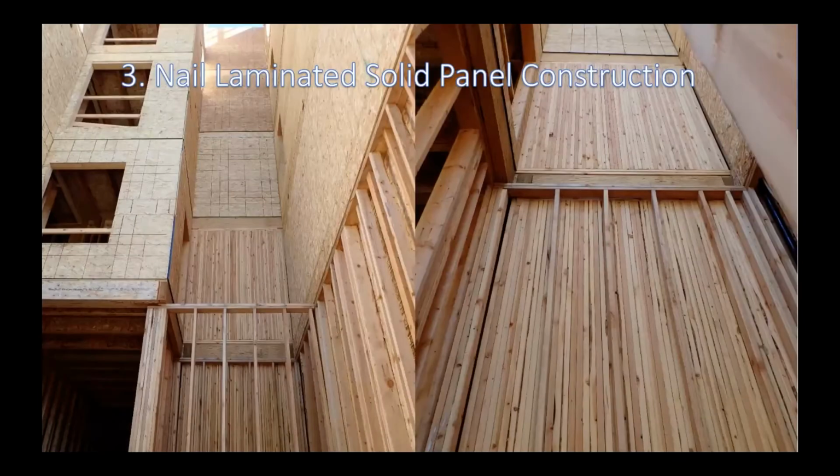And in less conspicuous means, there was a lot of nail laminated timber panel being used as well. Nail laminated solid panels are basically just simple 4x2s, or 90x35s or 90x45s, whatever it is. Just one board at a time, one stick at a time, nailed to the next stick until it becomes a solid panel. And these are excellent for unidirectional action as a panel form, because it spans and carries good compression loads, carries very good face loads as well, bending strength in one direction. And they use it in a lot of different applications. Like this one, I think, was in a lift shaft to create a solid core.